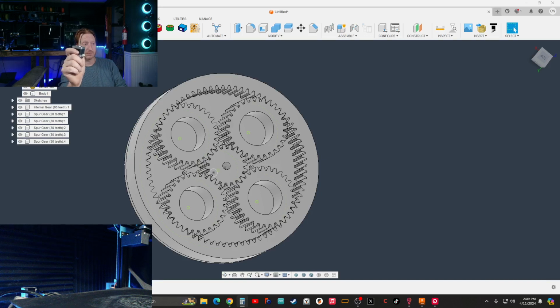No, it won't, because we have to factor in the gear ratios, the reduction. We would definitely have to factor in the reduction of the gearing, because it's not going to be 180 degrees. This thing's going to turn more because we're reducing it.